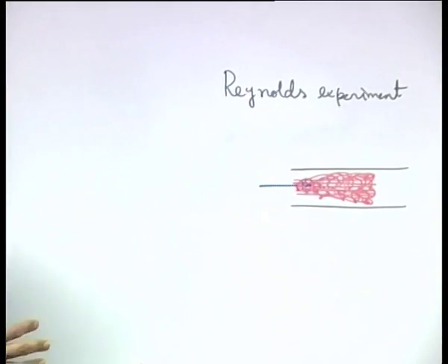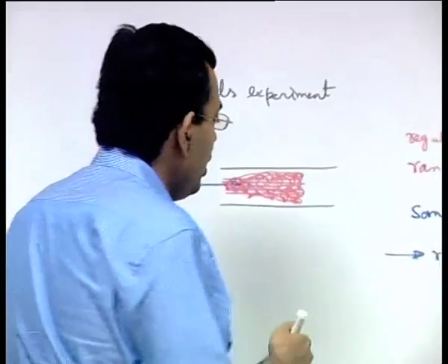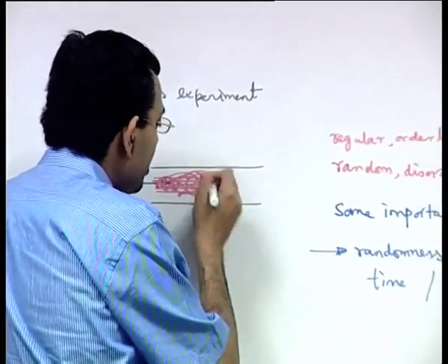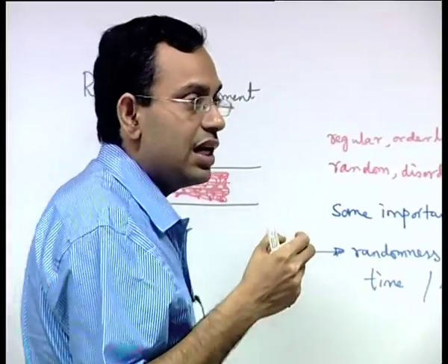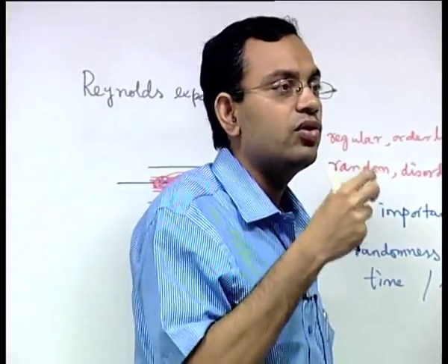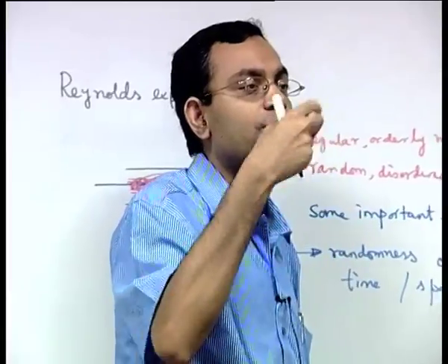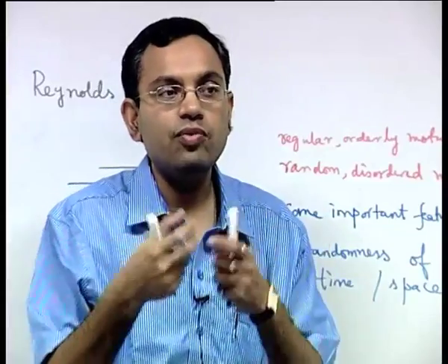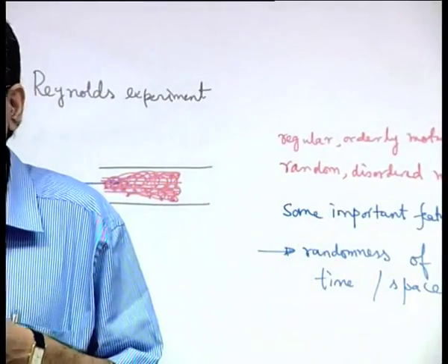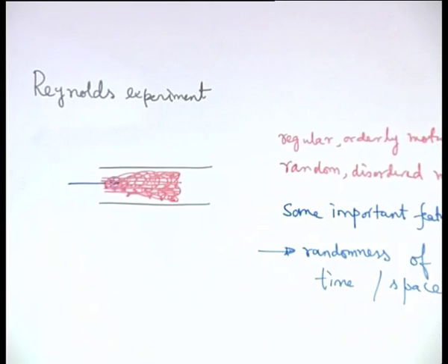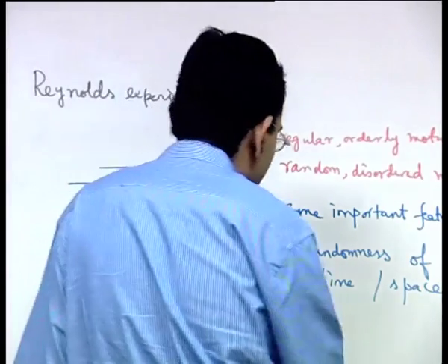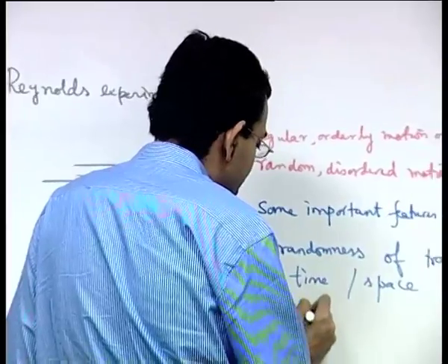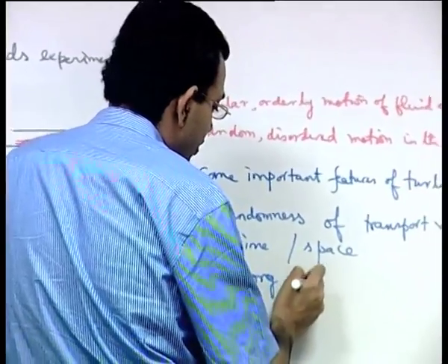So, when they are fluctuating, it is possible that because of fluctuation of velocities there is a significant amount of momentum transport between various fluid elements, because they are interacting with their fluctuating components of velocities, and in that process they are having an exchange of momentum, and therefore it ensures that there is a strong mixing in the flow.